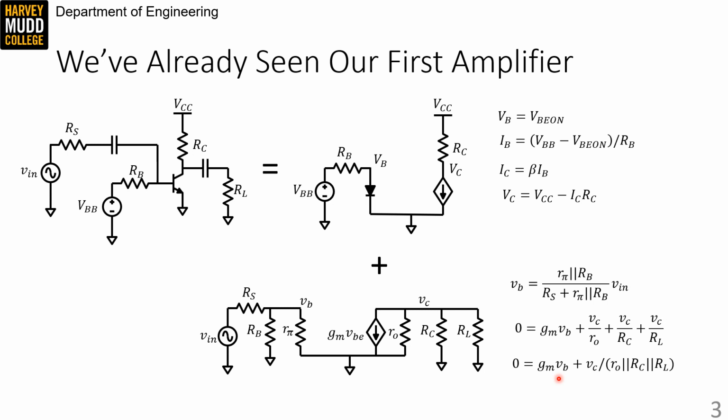We can find that coefficient by rearranging this equation a little bit. And we see that Vc is equal to some big coefficient times Vin. We refer to this coefficient as a gain. You may note that the gain is a conductance times a resistance times a dimensionless resistance ratio. So overall it has no units. That makes sense because this gain turns a voltage into a voltage. You might also note that the gain could be bigger than 1, because only one of these terms, this divider, is guaranteed to be smaller than 1. These two can assume any value, sort of in theory.